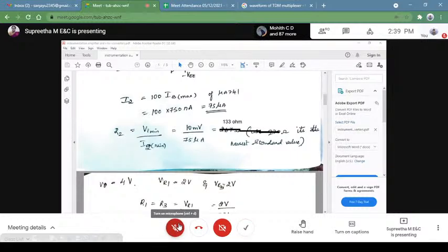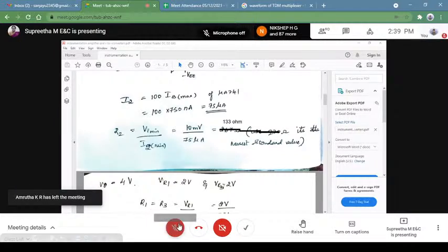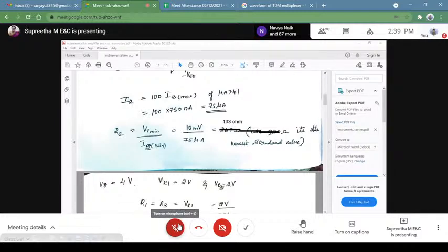So you get your gain to be 400. What is the formula for gain? One plus 2R1 by R2. So when it's 1 plus 2R1 by R2, so you know what is ACL, you know what is R2. Can you find out what is R1?